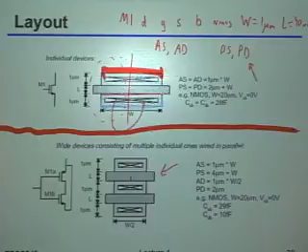Right? Because essentially for the same total transistor width, I've got these two transistors now in parallel, each of them with half of the width of the original transistor. So in other words, I've got current from this device as well as current from that device. I only have half of the drain junction area that I had in this particular configuration. Okay? Now notice, of course, on the source, I still have the same area as I had before.